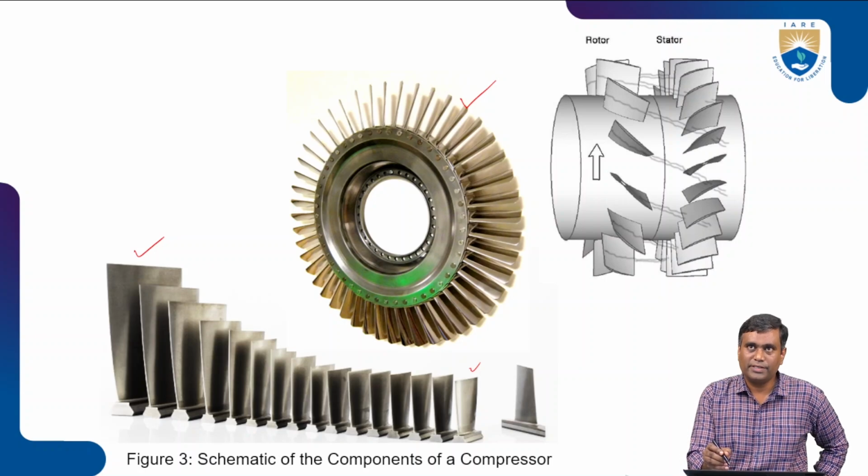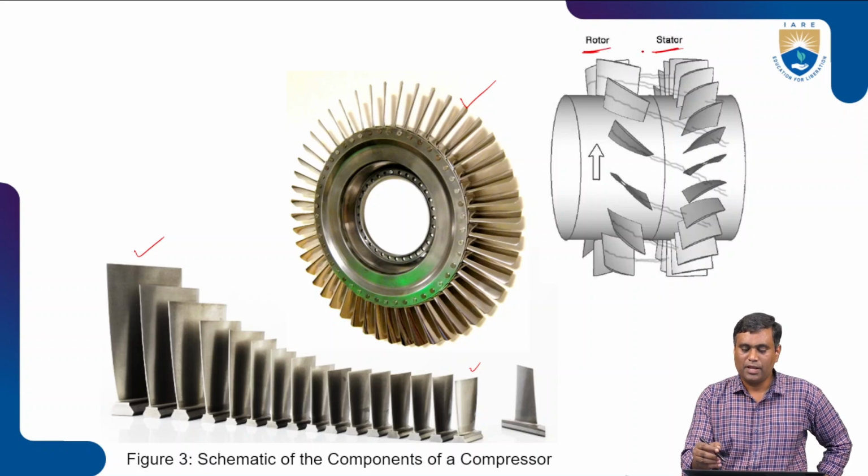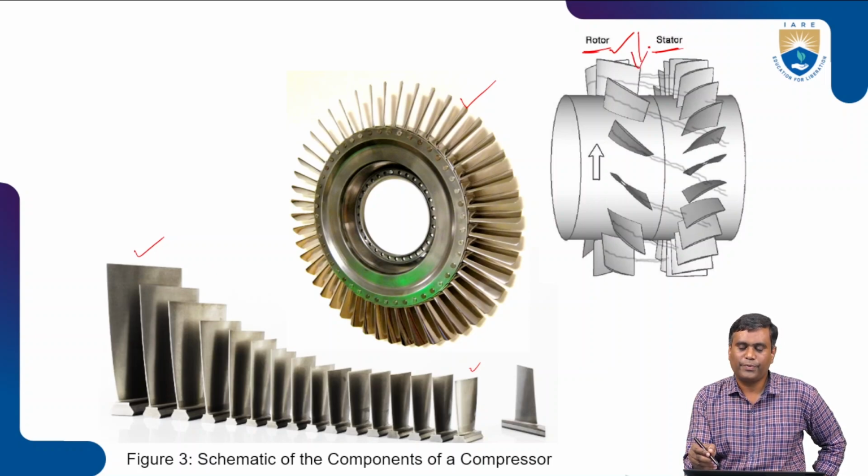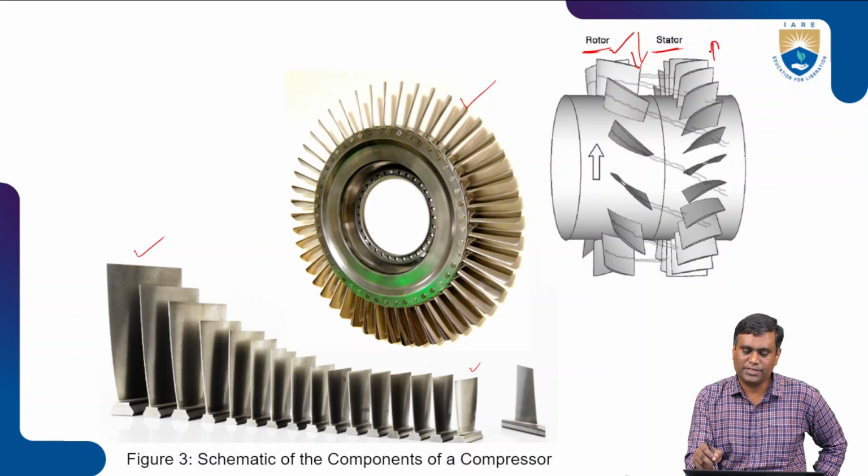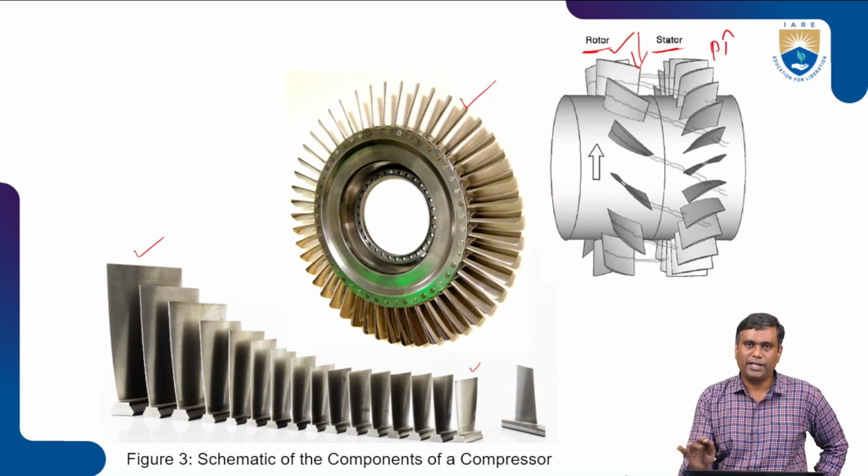And the arrangement will be like this: rotor and stator. As we have seen, rotors will increase the pressure and add kinetic energy to the flow, and then stators will decelerate it and increase the pressure further, and this repeats until the required pressure rise is achieved.